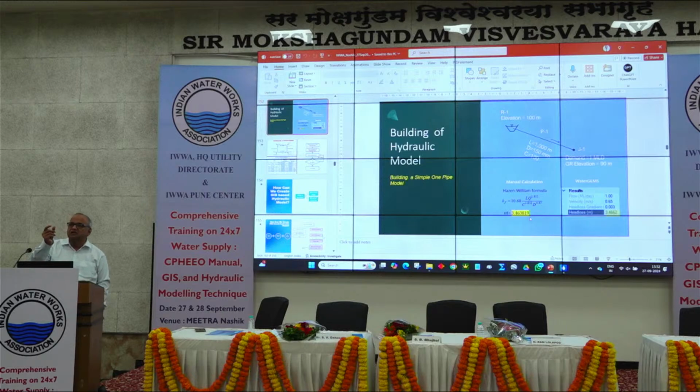If I increase the number of decimal points, it will show exactly. The point is, with the Hazen-Williams formula, it is giving 3.46, and in our WaterGEMS also it is giving 3.47. That means it is confirmed that the software is behaving correctly.